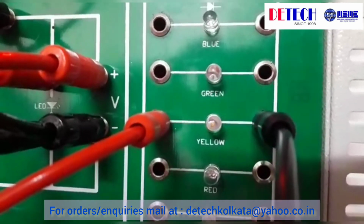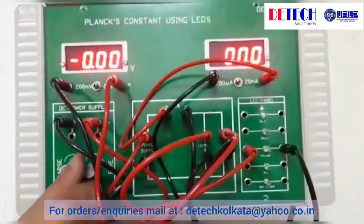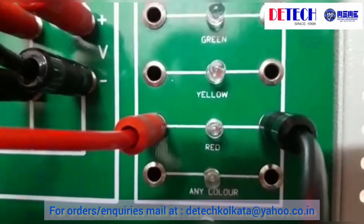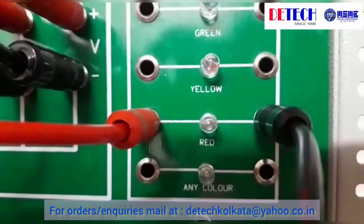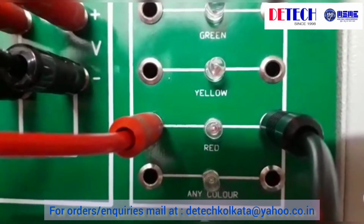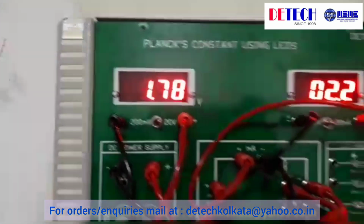so it has started to glow. So the voltage here is 1.92 volt and the current is 4.5 microampere. And for the red LED, the voltage when the LED just starts to glow, it has just started to glow. So the voltage is coming to be 1.78 volt and the current is 2.2 microampere.